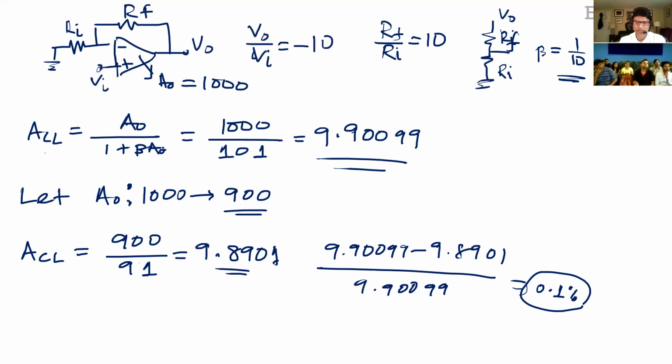We said the two major problems we had were distortion and gain sensitivity. So by putting in a large gain, putting this feedback with attenuator, we can actually have a pretty constant gain, right? So let's look at distortion now. For the distortion, like I showed earlier, it was a nonlinear transfer function, but I can linearize the model by saying, okay, I have some amplifier, I wanted a gain of A1, but not just did I get A1, I got this term VD along with that, right?